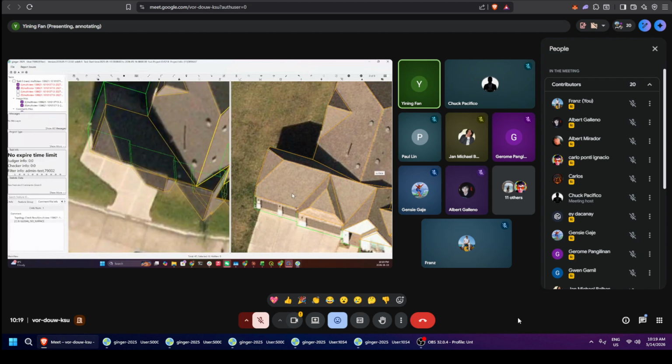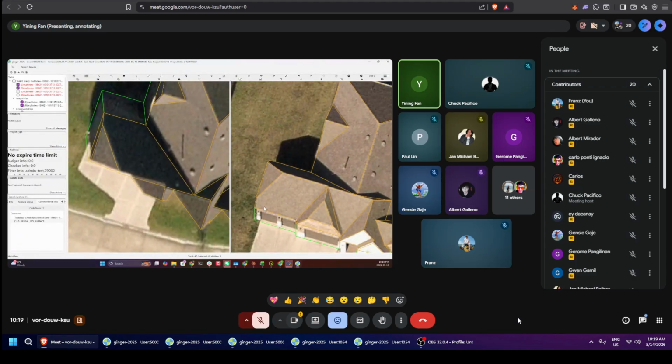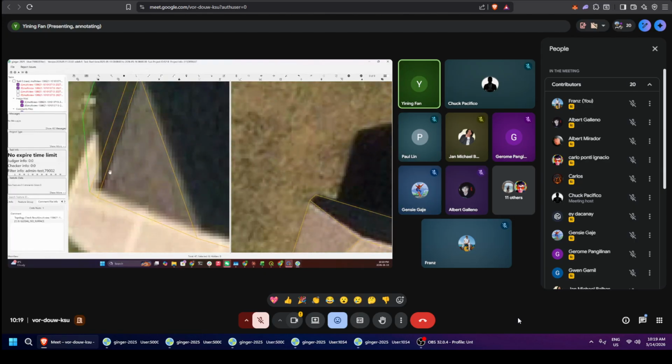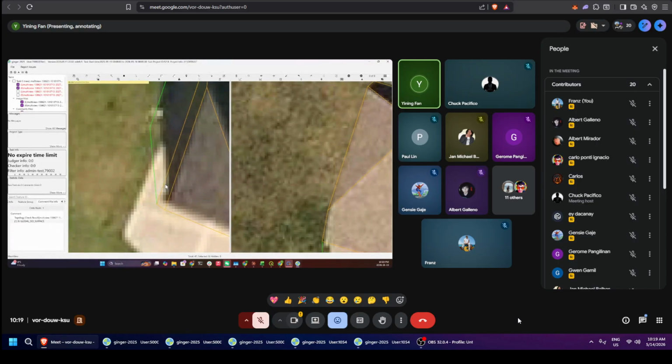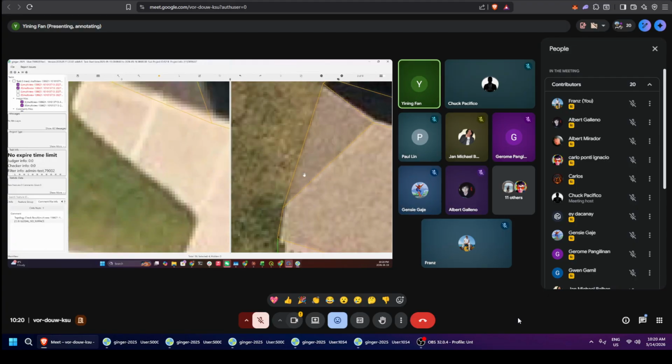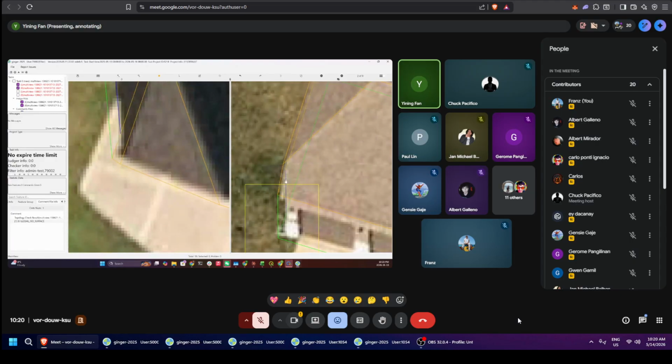To draw a new corner, the ideal thing is you find two angles that can see the same corner. Right here, one angle, the other one is right here. So we'd like to trace the wall at this location. Hold on. First using the assist line tool, just to find the actual wall location on this side. Then try to do the parallel, going all the way down, reach the bottom of the building. Then hit space. You will see a blue line drawn here. On the other side, if you want to see all the assist lines, just press Q and all the assist lines will pop up.